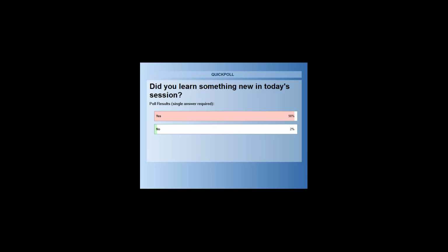Naman, feel free to throw out a couple of the questions that I may not be seeing. So a lot of them were, do these work with AEC objects, such as AutoCAD MEP or so on? That's a good question because when I was looking through some notes from somebody else, there was a big disclaimer saying don't try these with AEC objects. It may cause sudden exiting from AutoCAD. So I'd say try it on a drawing that you don't care about first. And if it works, then fine. But these were not designed in any way to work with any of the AEC objects. So if they work, they work. If they don't, they don't.